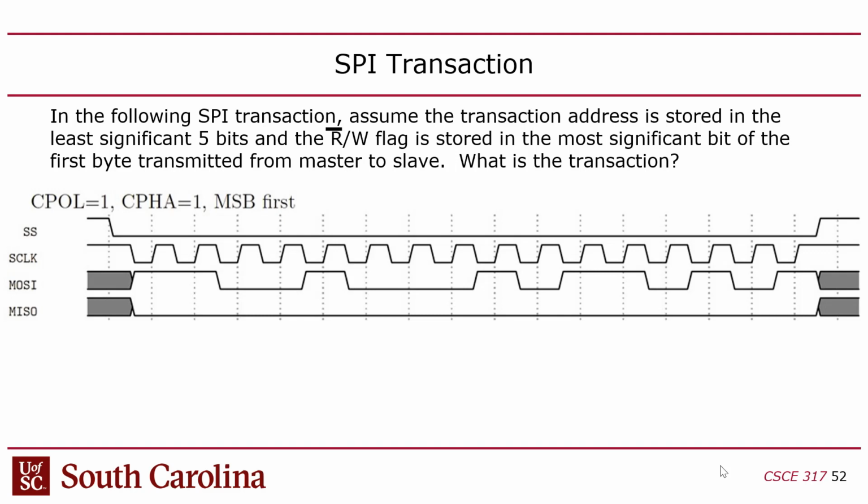And like I said, SPI doesn't define what the bit ordering is that you send across. Now, I2C and UART do. So some protocols do specify the bit ordering. SPI doesn't, so we have to list that here, right? And usually if you're using an Arduino or a Raspberry Pi, something that has an SPI endpoint on it, an SPI channel, that's something you program ahead of time. Well, you or the device driver programs that in the hardware, sets up the hardware for these settings. And of course, you would have to tell it ultimately what those settings are from the data sheet of the device you're trying to talk to.